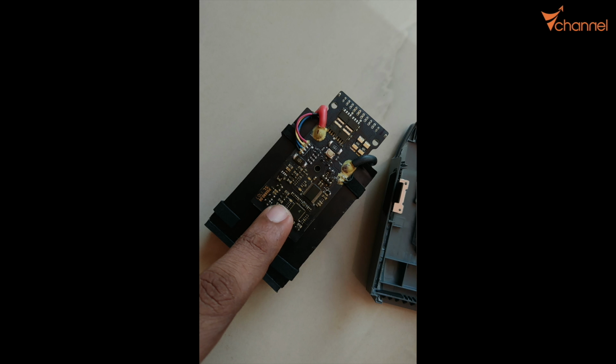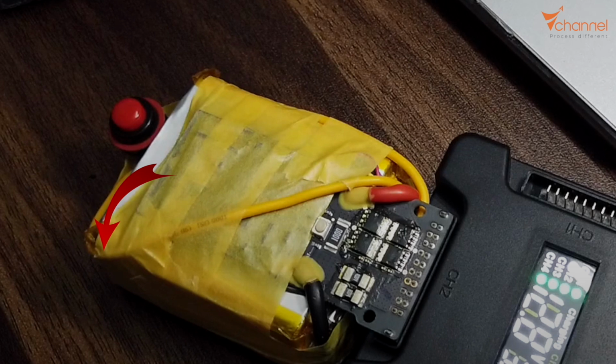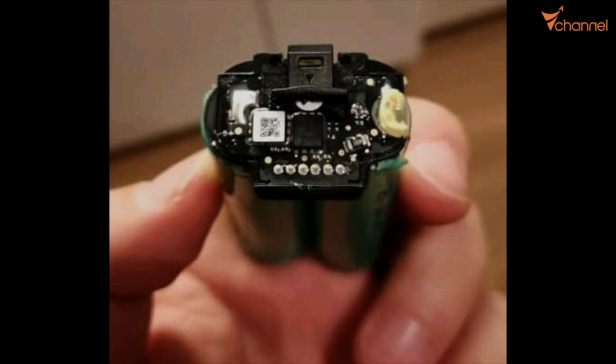We must keep the power supply connected in parallel continuously while removing the original cell. Or another method, if unfortunately the circuit is locked, we must have another wire connecting positive through the original board, unless the board is disabled. However, Mavic Mini is easy because it has no lock circuit at all. I'm not sure whether DJI will add a function to this circuit in the future or not, but at present it's not there.